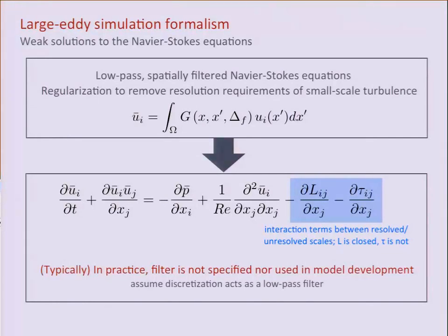But in practice, typically, this is not always true, but it's peculiar because although you derive this equation from some low-pass filtering of the NS equations, this filter is not specified during simulation, nor is this idea of the filter, what filter you used, in the model development, or the way you derive what models you should use for these unclosed terms.